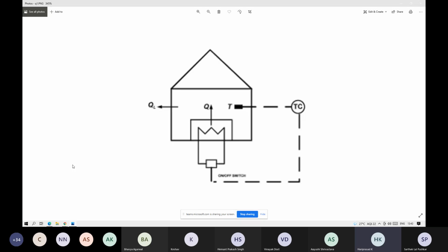Heat is not a true variable. It is a latent variable, in the sense that, unlike temperature or pressure, you cannot measure heat directly. You will have to measure something else and act on that. An increase or decrease in heat basically helps you increase or decrease the room temperature. So absolutely, it is a manipulated variable, because that is the one thing you manipulate. But the question is, how do you manipulate it? Technically, the increase or decrease of heat gives you the increase or decrease of temperature.